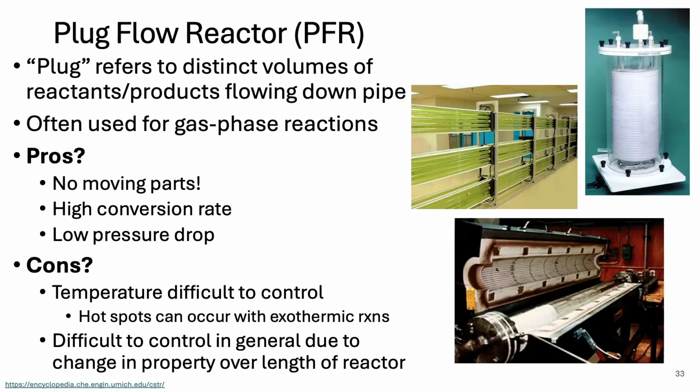Another main one is we can achieve high conversion. So unlike the CSTR, which operates through the outlet conditions, in the PFR the concentration is the same throughout each plug. And again, it's just changing as it goes down the length of the reactor. And other advantages, they have a low pressure drop.